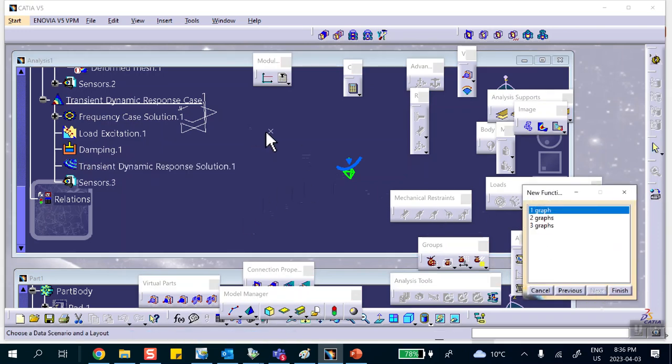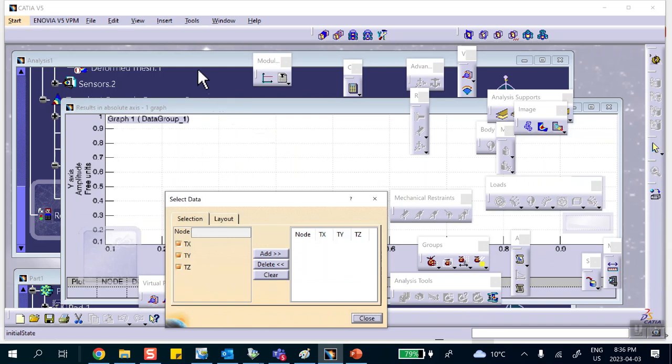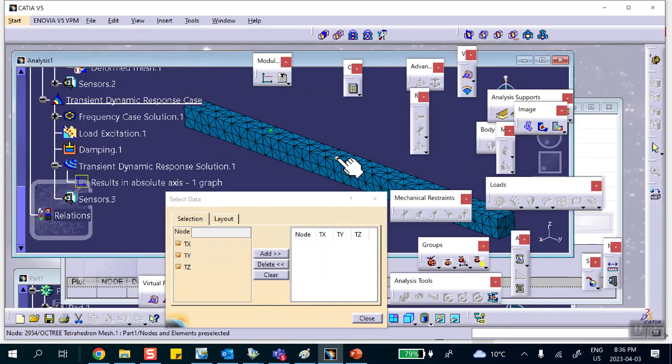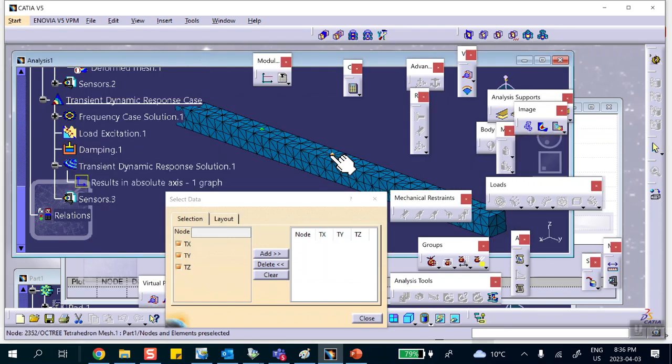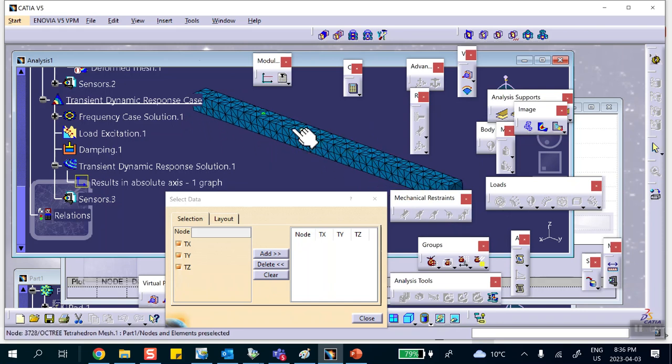My mistake was that the point that I created and put the load on, I put it in the middle. It should have been the quarter point. That's why I have to do a cleanup basically. So we go here. Now the place that I want to monitor is halfway in the middle. If you're having problems finding this, what I suggest is you create 2 points. One of them is for monitoring purposes. The other one is for applying the load. You understand what I'm saying?